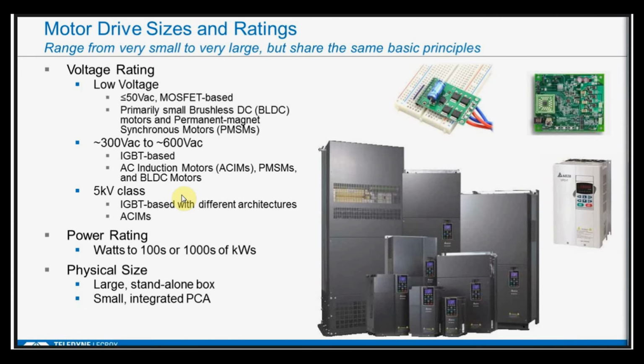One last comment about drives. A lot of people may have a misconception about what a drive can be. We talked about these very simple H-bridge type circuits for single phase. Well, here's a very small single phase motor drive. You can see 4 devices right here on a board. Here's my DC bus capacitor. Something this simple is not so uncommon.